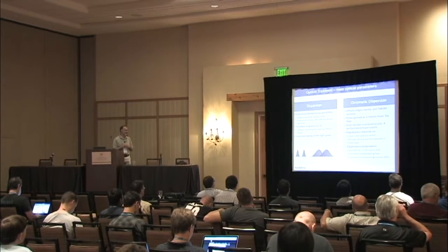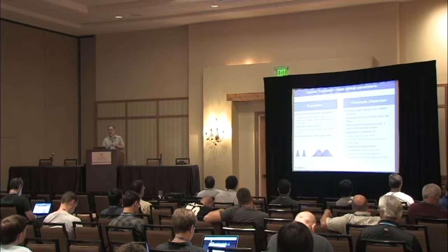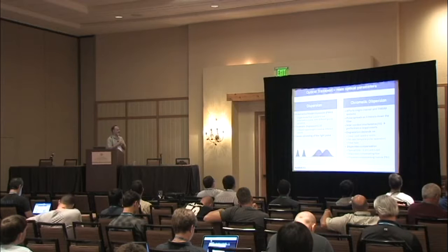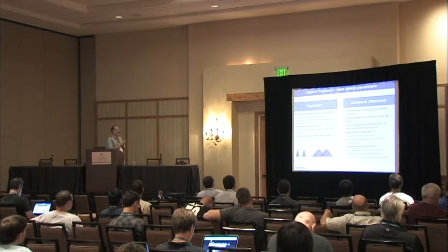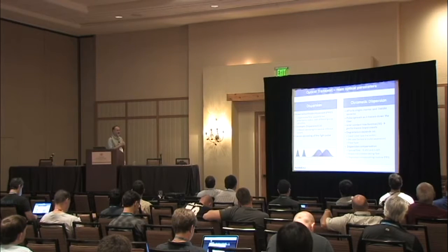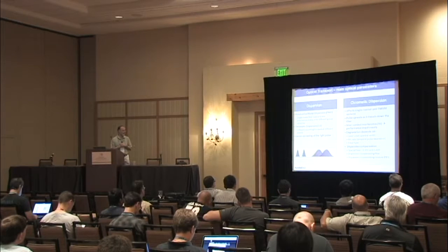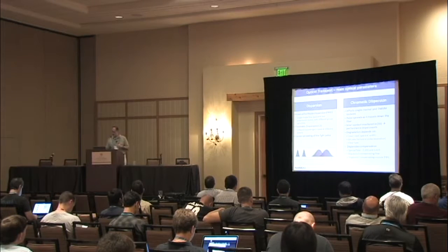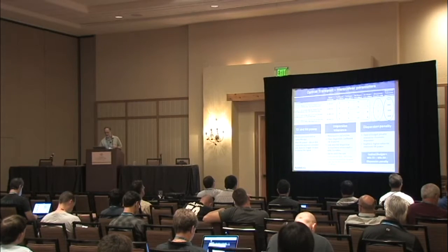How do you compensate, mainly for the chromatic dispersion? As I mentioned, special fiber, you have those two types of fiber. One is zero dispersion, the other one is low dispersion. That can help manage this dispersion. And then you can have dispersion compensating fiber. You basically put a small spool of fiber that causes the signal to go back to the nice shape. And the same compensation is done by a dispersion compensating module that has fiber grating inside.